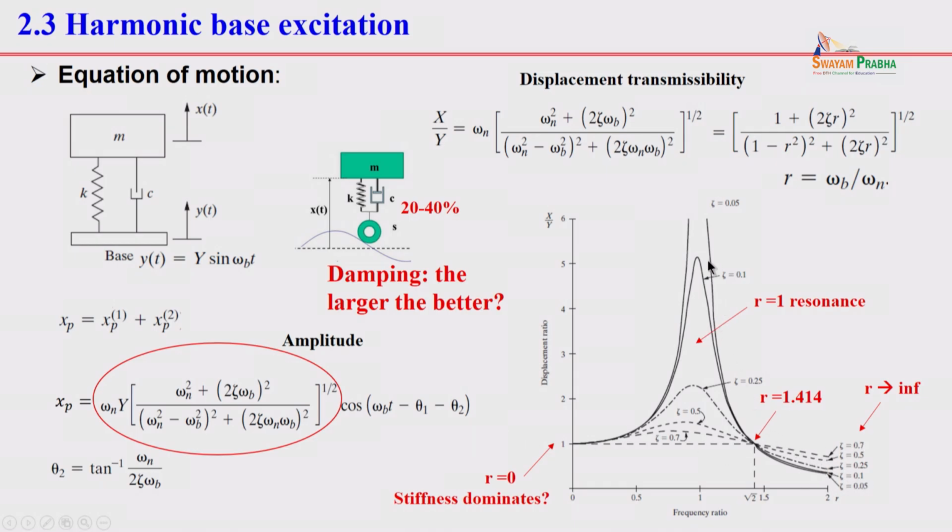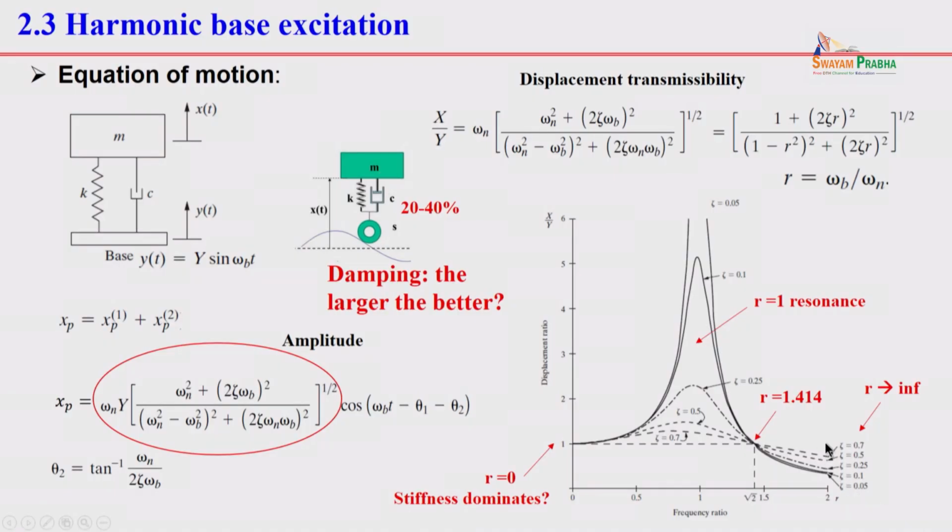If you have small damping, the amplitude will be lower. And at high frequency, if you have larger damping, the vibration will be larger. The reason is, in a car suspension like that, at larger frequency the shock transmits from the ground to the car body. So therefore, if you have more damping, the amplitude at high frequency is worse.